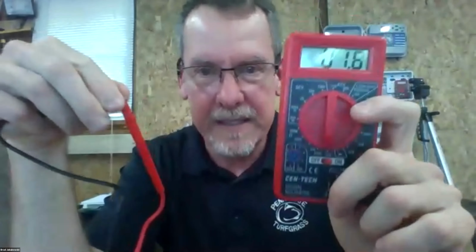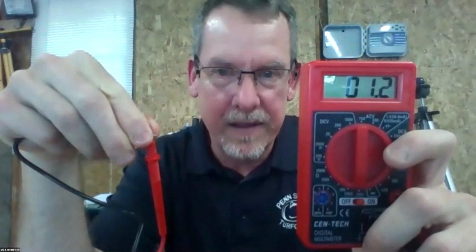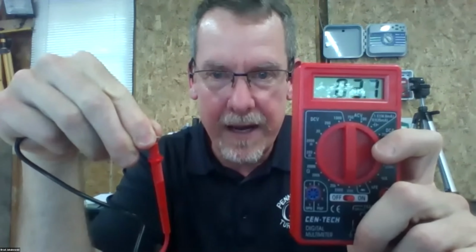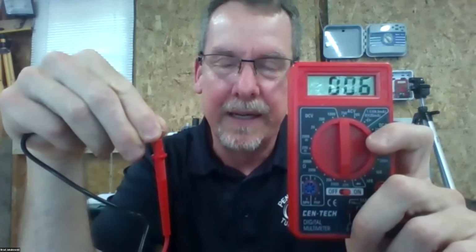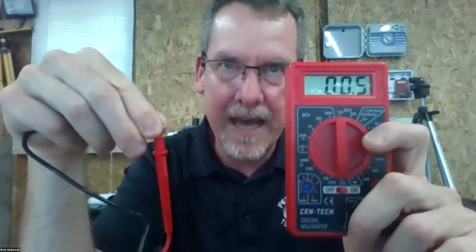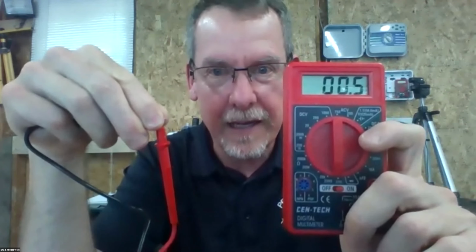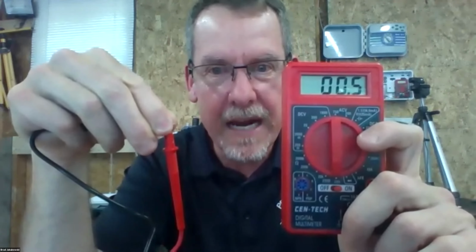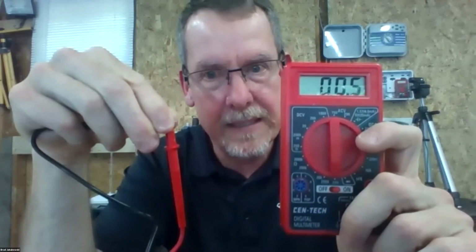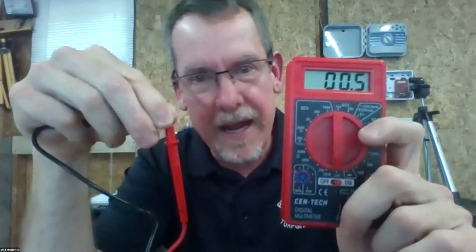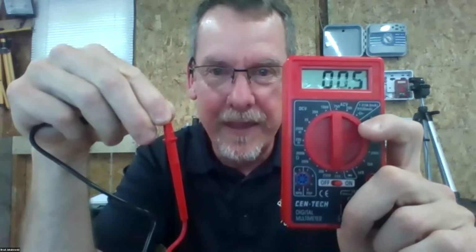So one of the things that we could do then is test the precision of our multimeter. We cross the leads and see how precise these multimeters are. Mine right now is bouncing around a little bit, and you can expect that, but it'll go down to about 0.6. So 0.6 for this particular meter is telling us that when you get a short reading, the lowest it may ever read would be like 0.5 or 0.6. The other meter that I was just using probably an hour ago, the lowest that it would read was like 1.3.